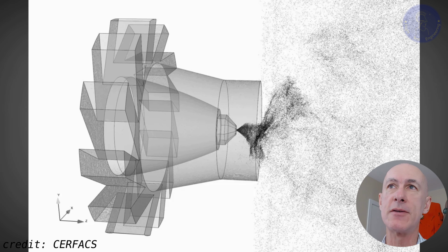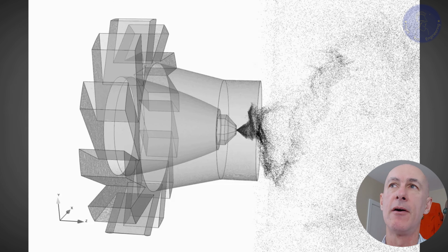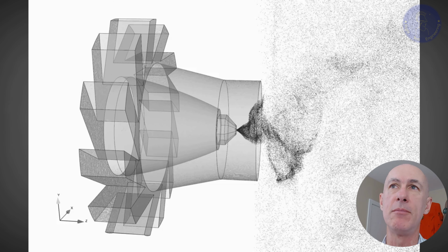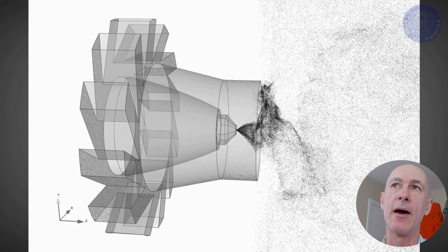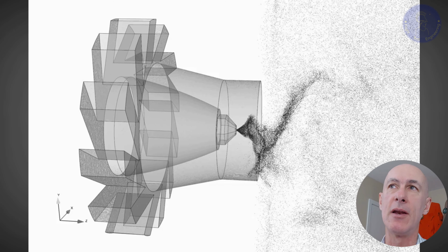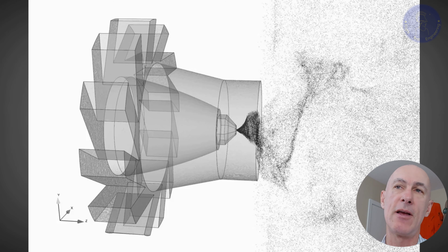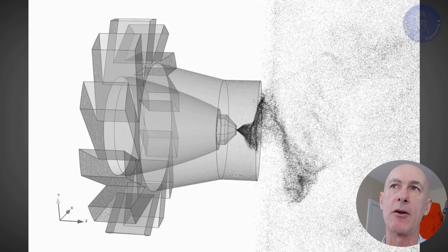Next, the fuel is atomized and injected to mix with the swirling air for a short period of time until it meets the flame front and ignites. And as the flame travels downstream, it is recirculated from the sides. That's effectively creating a feedback loop.